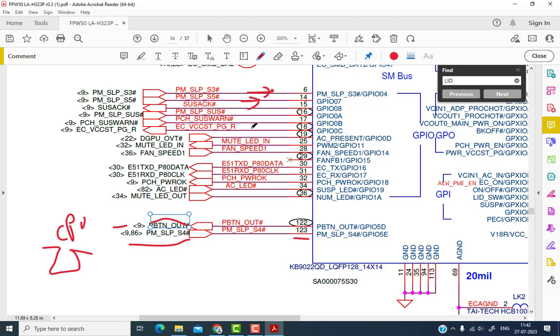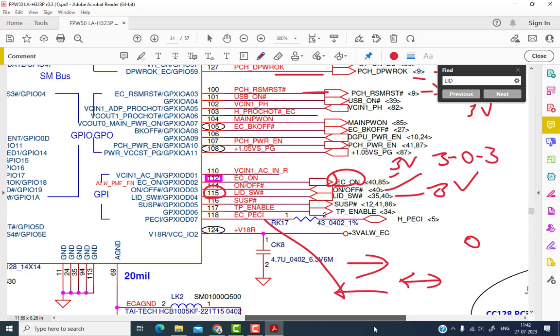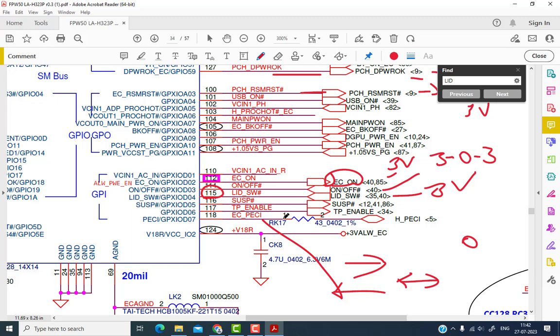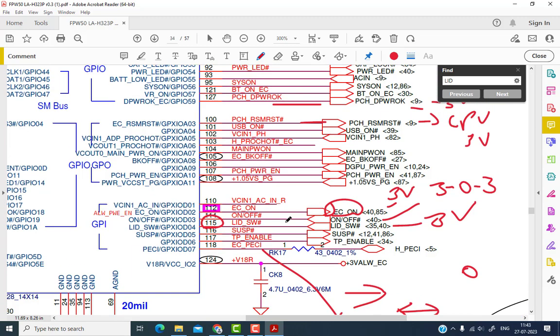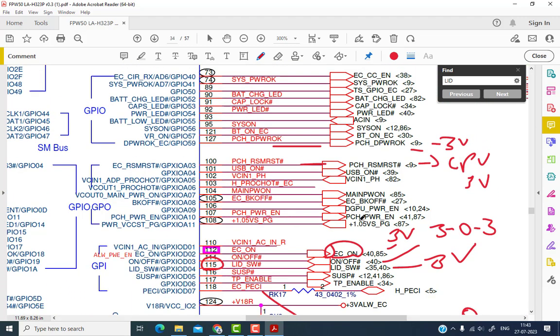So in this way, when this signal goes from 0 volt to 3 volt, that means the CPU has given the confirmation to the SIO to turn on the rest of the supply. Okay, so after that SIO starts turning on the different buck converters. So we'll see where the signals are. So here these are the signals, and the first signal SIO generates is called system on.